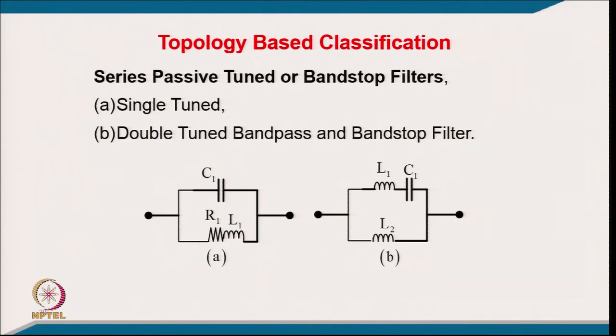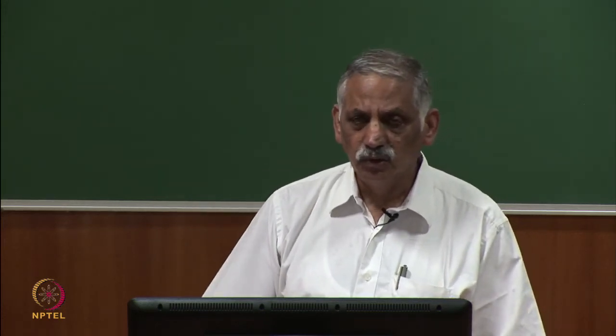So, it can block 5th and 7th, but keep in mind at fundamental frequency the impedance of this will be inductive. So, it will take some inductive voltage drop across it, if it is not going to harm. That is the reason earlier it was not too popular in the current fed load. Why is it not used with the current fed load?